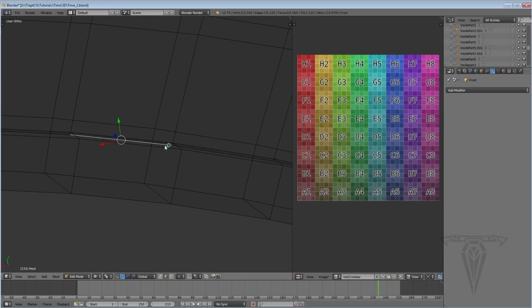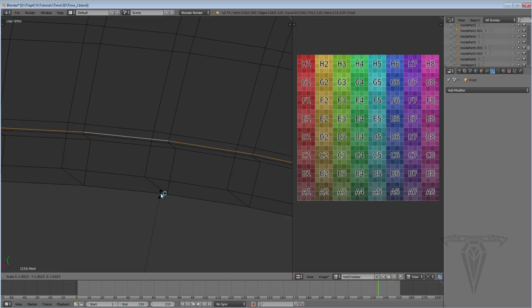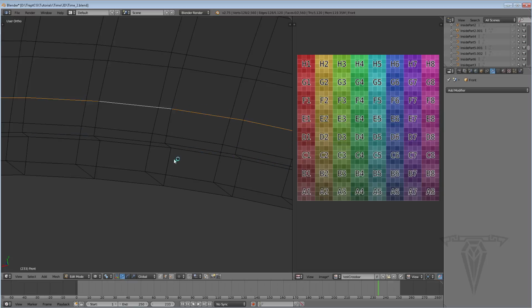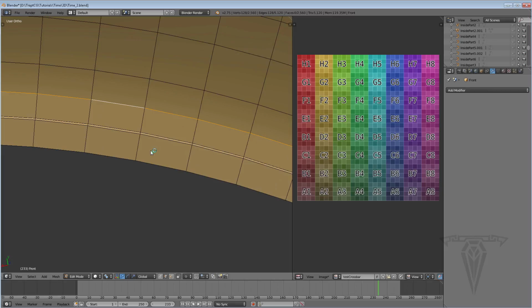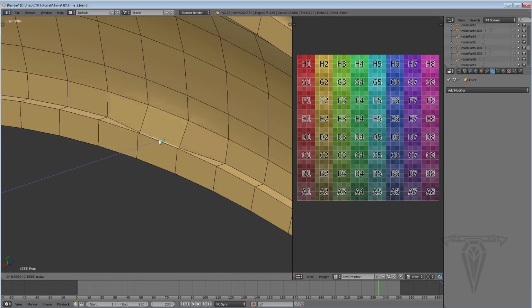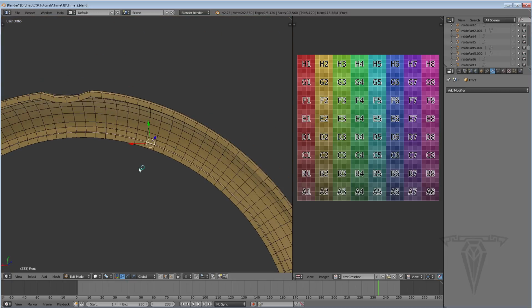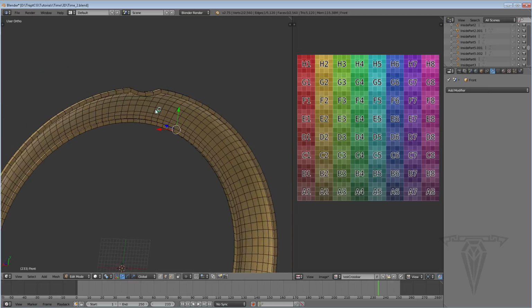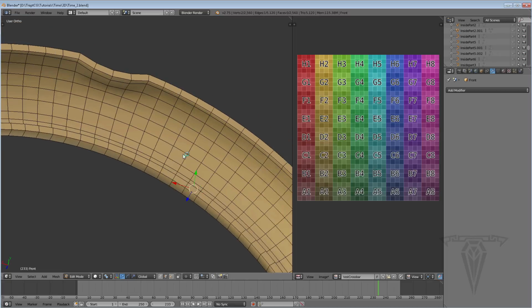Okay, and what it looks like is this edge is on the inside and it needs to be pushed out. So I'm going to Alt click it so it loops all the way around, and I'm going to hit S on the keyboard to scale it, and I'm going to scale it up to maybe right about there. Now let's hit Z on the keyboard to come out of wireframe mode, and that looks perfect. Maybe even scale a little bit more, right about there. So if I grab this edge now, and let's just move it to make sure. Yeah, I've got no weird geometry hidden within geometry. Okay, so it's just something to pay close attention to, and that was caused by the solidify modifier that we added, by the way.